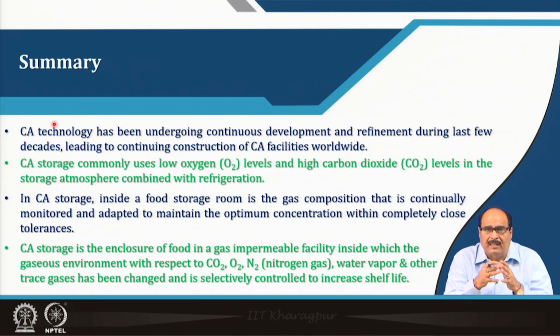In fact, it is being encouraged that most cold storage units should be converted into controlled atmosphere storage units. So, you have the temperature control, along with that O2 control, CO2 control, etc., and there should also be humidity control. If all these things are properly controlled and maintained at the desired level, you will get the benefit.